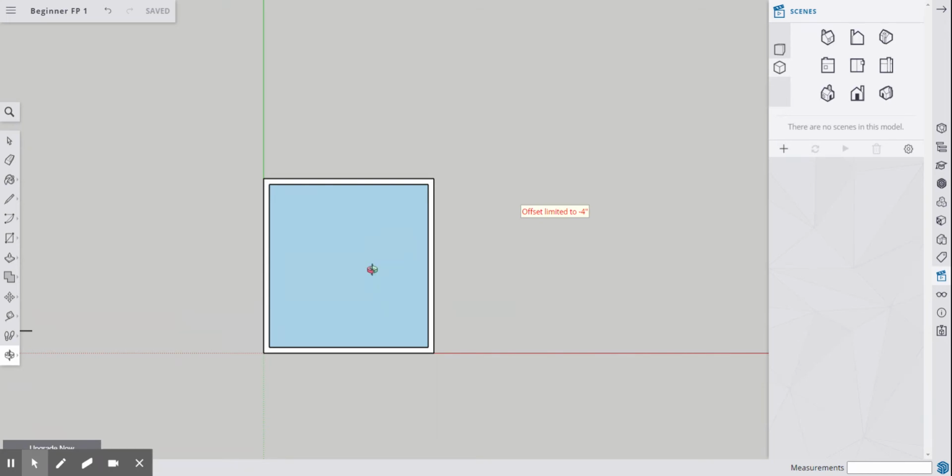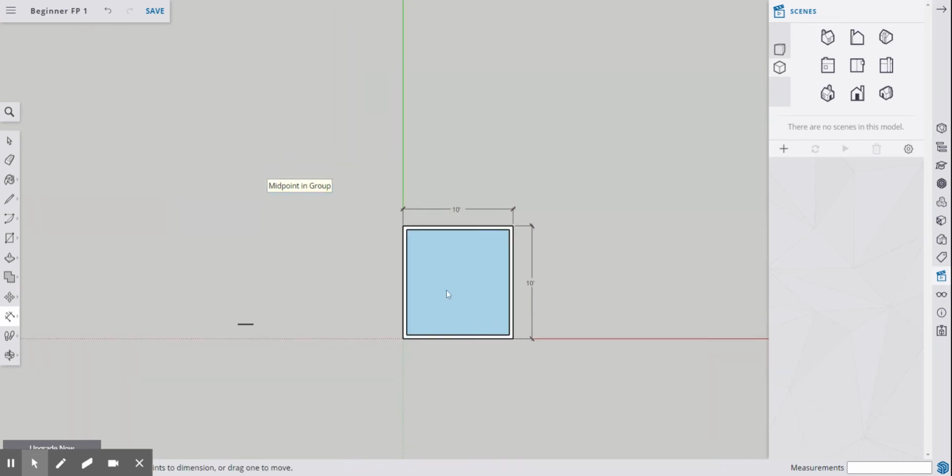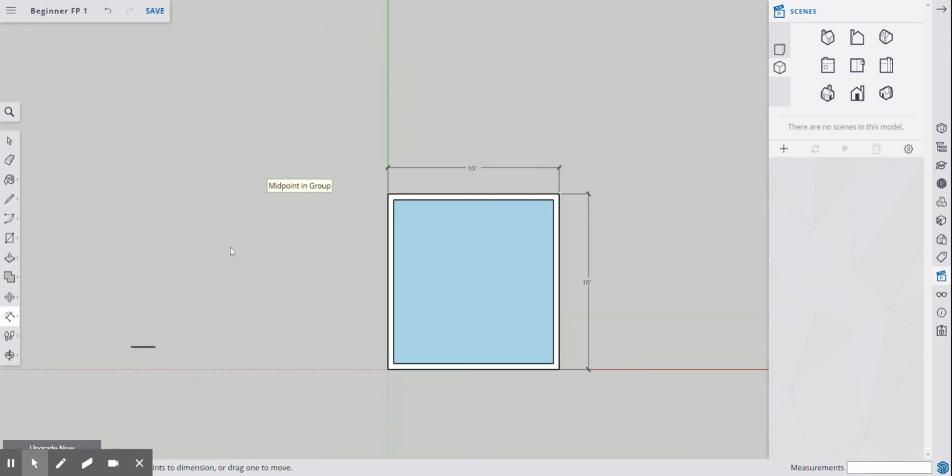So what that gives you is just the straight top view, and this is what we need, okay? So we're going to work on dimensioning and getting different views. So start with the floor plan, and how we dimension is instead of using the tape measure, this little dimension line with the 3 actually keeps your dimensions there. So let's click it, and we're going to dimension this point to this point, and then we're going to dimension this point to this point, and then obviously the others are the same. So that's our dimensioned plan view.